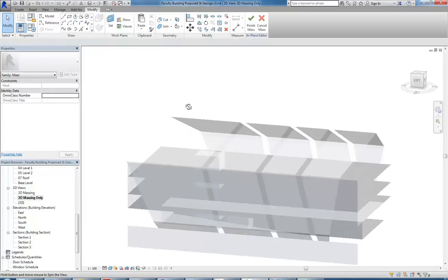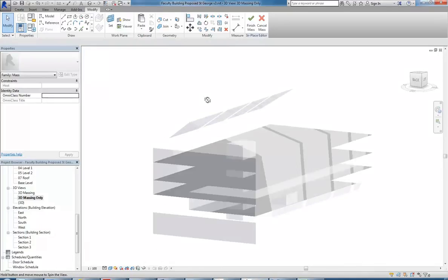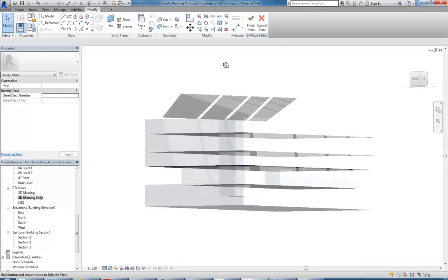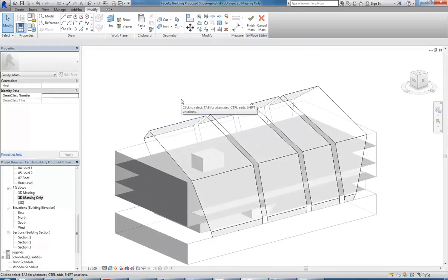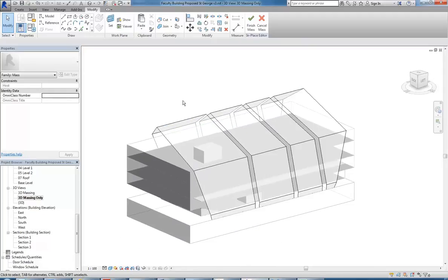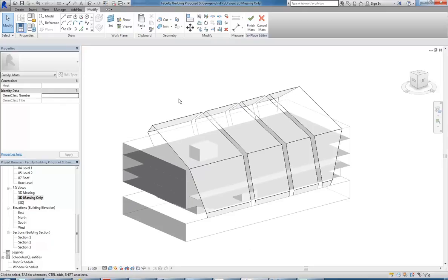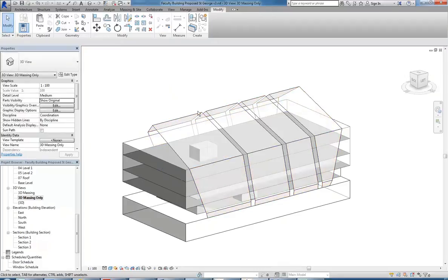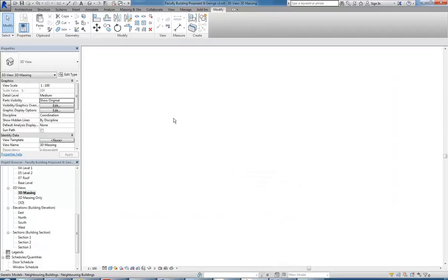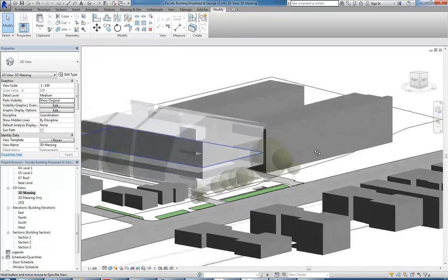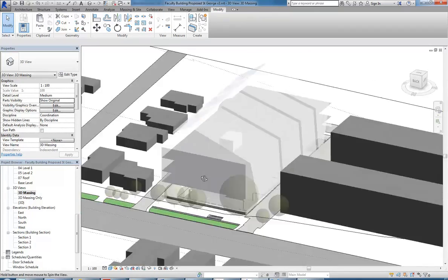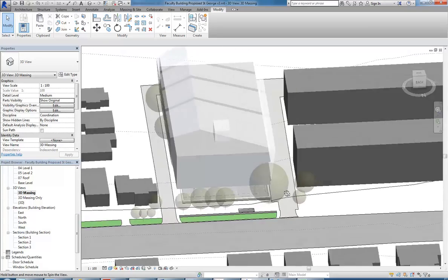And again, you don't have to do massing to create walls and floors and roofs and ceilings and all the other main elements that are going to define your building shape. But if you have to create all those other things just to work out the form, it is usually much harder and it's a lot more work, particularly when you're making adjustments, instead of just doing it with something simple like massing. It can be simple anyway, with massing, and then we can have a look at how that fits into context before committing to making walls and all the other things.